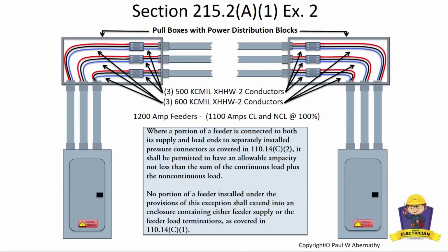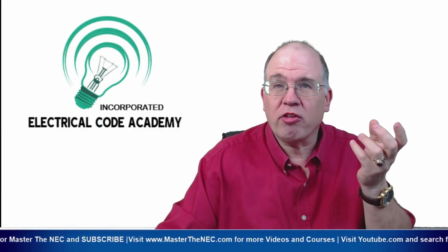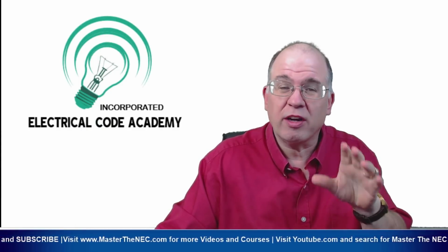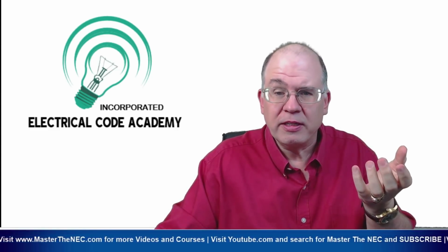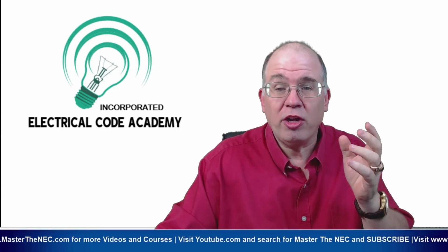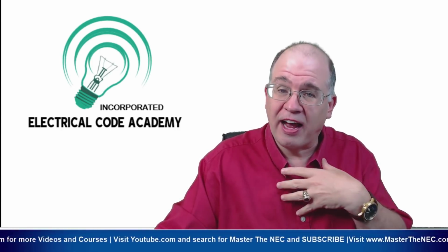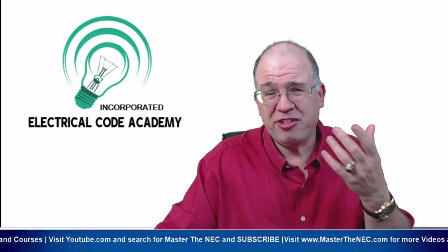Now, I'll bring it back to me and just explain a couple things. Voltage drop is not a mandate by the code, except when you get into fire pumps and other types of applications where it specifically mandates it. Most of the time, it's an informational note. And under that informational note, it's not enforceable. However, it's a good design aspect that should always be considered, but I can't reject you for it.